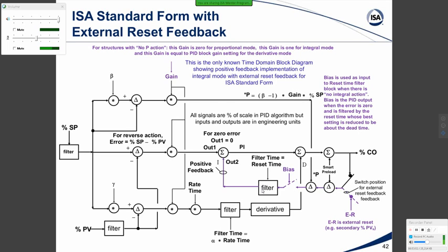We had filters by means of restrictors and bellows. So we could implement a filter. So all pneumatic controllers had this. And then when we moved to electronic controllers, they said, oh, now we know we can make an integrator. And so they stopped doing this, not realizing all of the features that they lost.